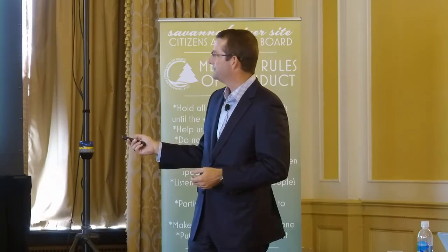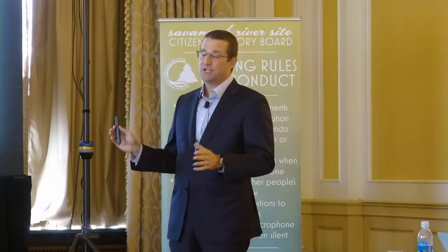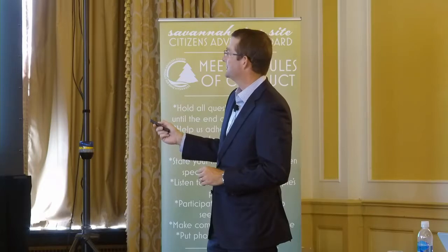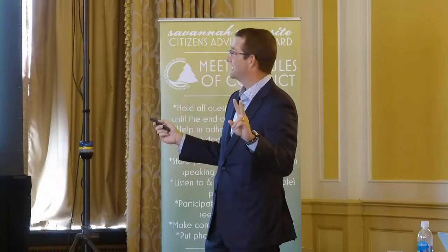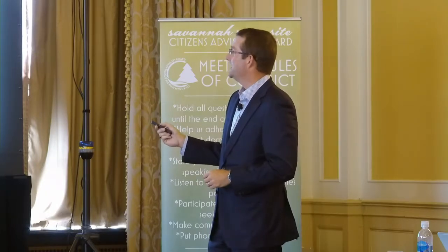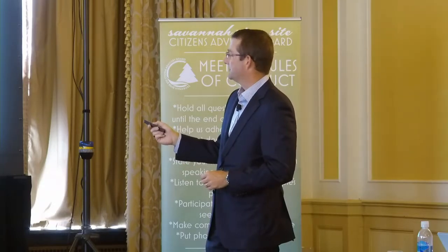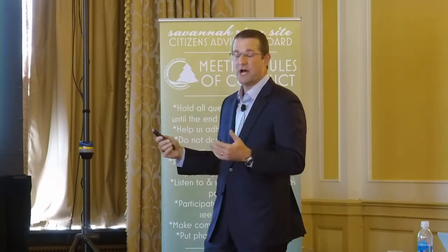Coming out of the screw feeders, that premix is discharged into our mixer. This is where we have our first interaction from the wet side of the plant. We will be simultaneously, today, we receive from the tank farms the decontaminated salt solution into a salt solution receipt tank. We actually have 2 of these vessels. I'm only showing 1 for clarity. These are 60,000 gallon vessels. They have their own supplied transfer pumps that provide flow to the mixer, which is where you now contact the dry material in the liquid feed.